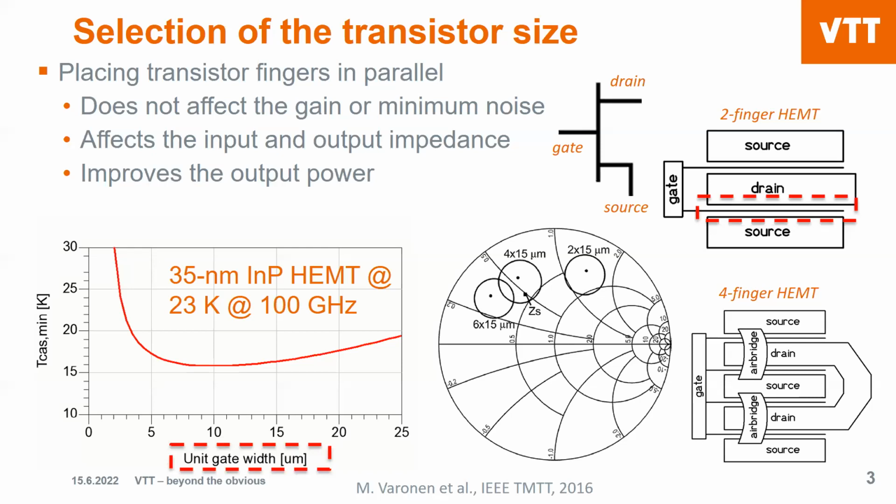And we can see that using this transistor model, if we scale down the finger width, actually the noise shoots up. So typically, ideally, you would use as short a finger as possible because you decrease the resistance of the finger. But in a real transistor, once you scale it down very small, the capacitance starts to dominate and other external parasitics, meaning that the scaling does not work anymore and you get higher noise.